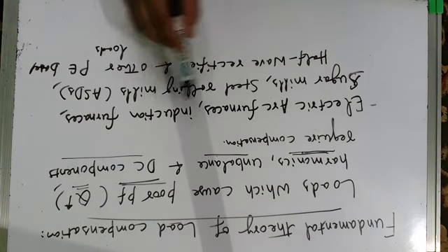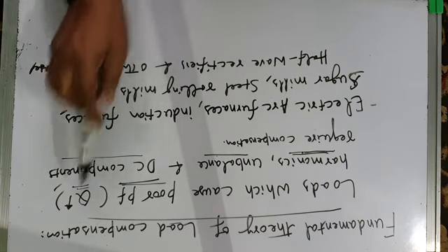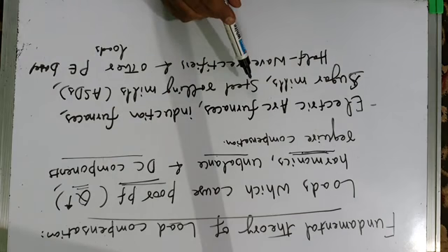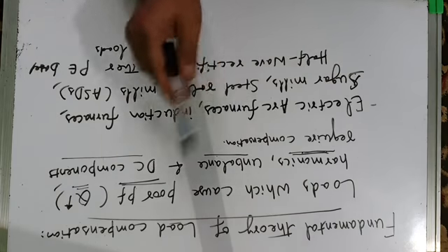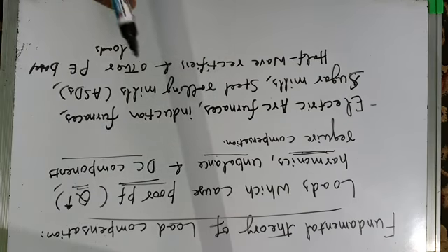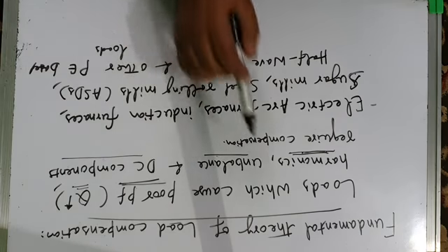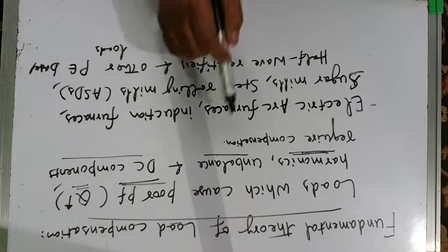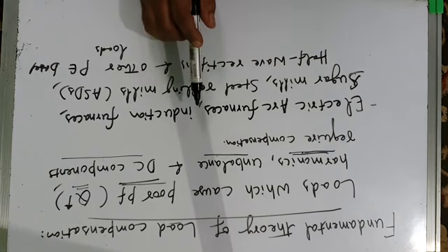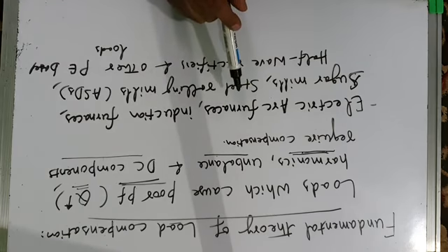Electric arc furnaces and induction furnaces, they cause harmonic injection. Sugar mills, steel rolling mills using adjustable speed drives, they cause harmonic injection and also poor power factor. And then unbalance also may be there in the system. If you have a three-phase four-wire system, if the single-phase loads are not properly balanced, distributed, that will cause unbalanced load. And unbalanced load will result in unbalanced flow of line currents, and hence that will result in unbalanced voltages at the point of common coupling.